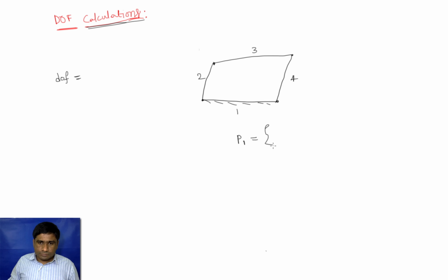p1. We have a hinge joint between link 1 and 2. Here the degree of freedom is 1 when we have a hinge joint, because it's constraining the translation motion in the x and y direction. So this link 2 can rotate only about this point O with respect to link 1. So links 1 and 2 constitute a pair having only 1 degree of freedom.